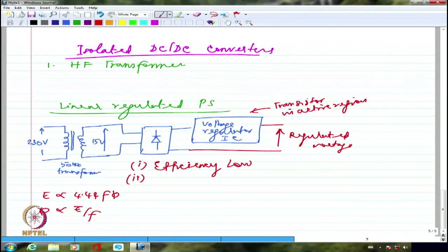So obviously, because the flux requirement decreases with increase in frequency, the transformers would get miniaturized. They will become really, really tiny when I go for larger and larger frequencies. That is one reason why, I think I mentioned this definitely in the electromechanics class, aerospace electronic systems or aerospace machines generally, whatever is used in aircraft, they all operate at 400 hertz. They never operate at 50 hertz. Okay, so it is like a trade-off.